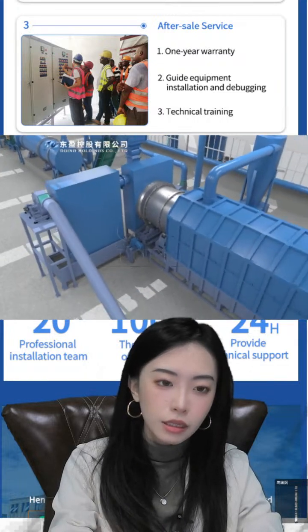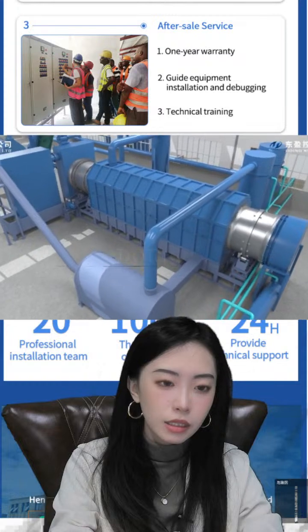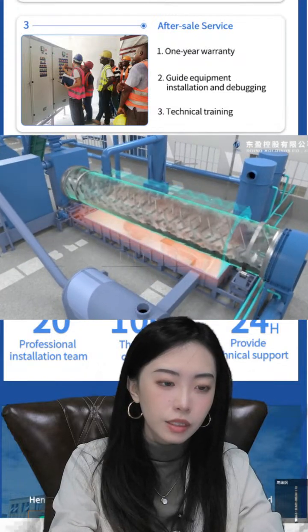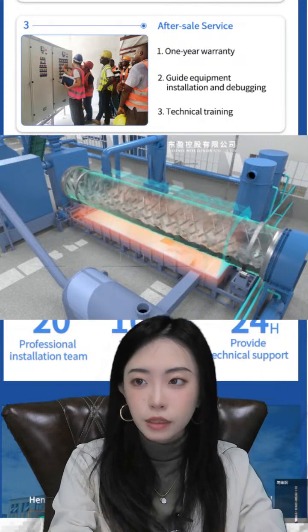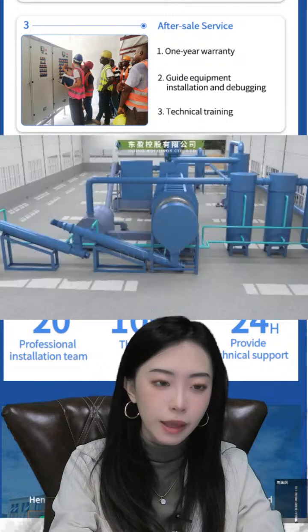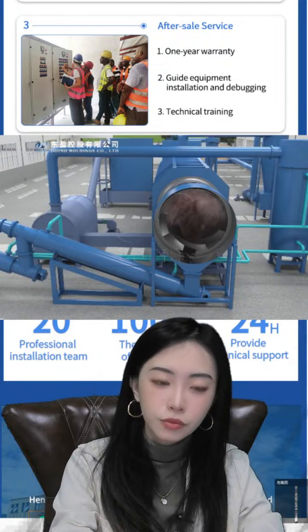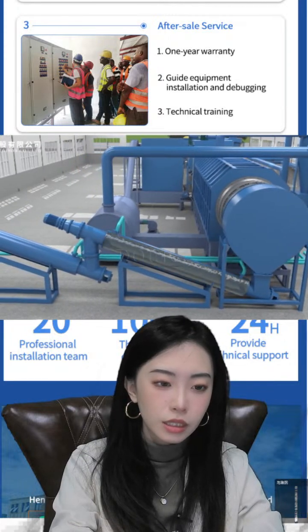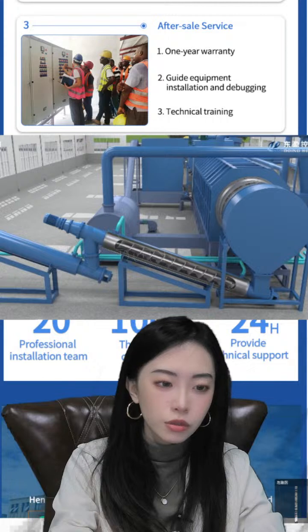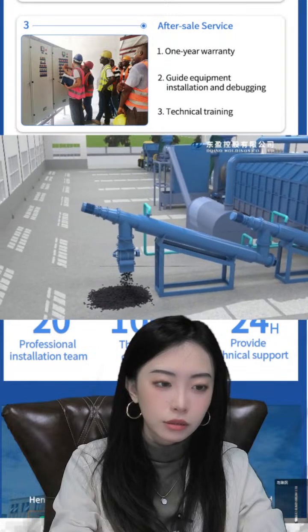And then this is the carbonization furnace. The heating uses a hot air heating furnace, and the equipment is indirect heating. The chamber temperature is 400 to 600 degrees, with the front higher than the back of this reactor. A screw is used to discharge the carbon black, and in the slagging section, we use 1 or 2 slagging winches with a condensate cover outside to cool down the slag.